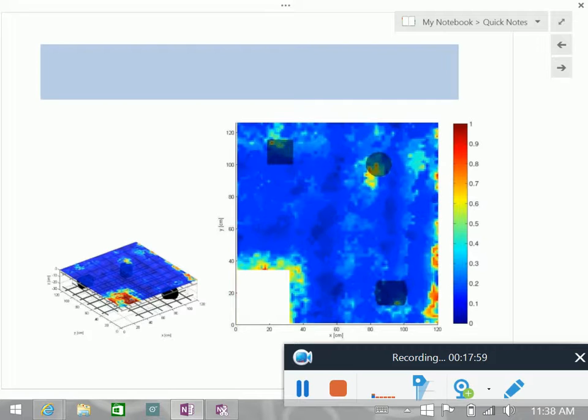However, for this kind of application, it's not as good as ultrasound. One reason is that you can see there is a location problem. Impact echo is an impact-based test, so it's affecting a larger area around it. It's affecting a volume, so the spatial resolution is not as good. But it's very cheap. That's why people use it, and it's very, very popular.